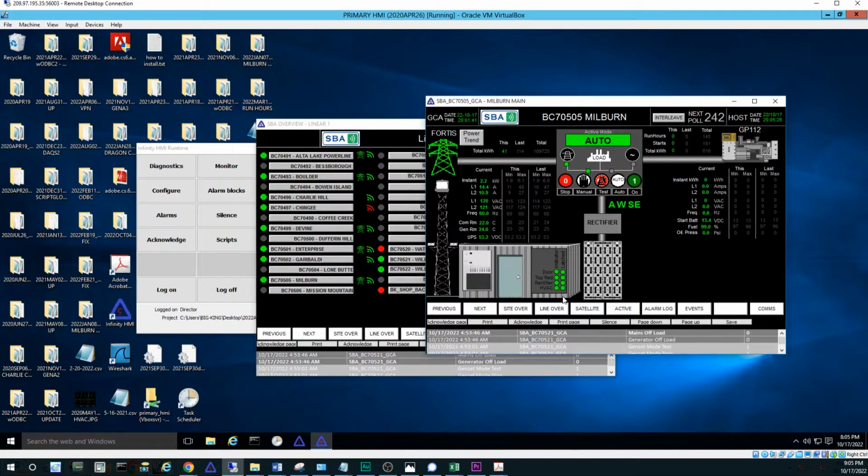We have 4 letters that indicate generator issues and are labeled as alarms, warnings, shutdown, and emergency. Warning and alarm is related to high versus high-high set points. Shutdown is a scenario where we would shut down the engine to prevent damage such as low oil pressure or belt failure. Emergency might be a fuel leak or something of that nature.